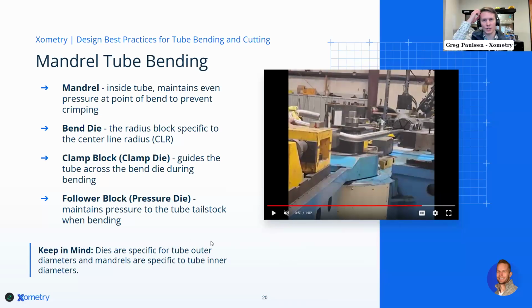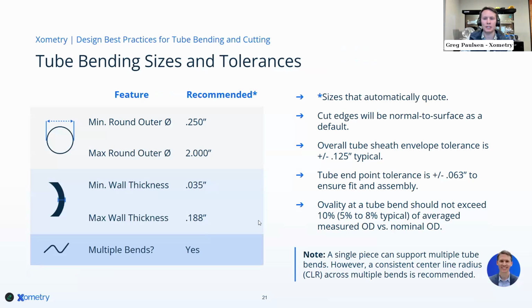And I think what's really important here is that this is very different from the hand bending tools you may buy at Home Depot. This is where you're looking at advanced manufacturing technology, because once you have these tools and setup, you can repeat and repeat and repeat with this. It is very powerful for multi-bend tubing at low volumes, but it really shines when you're outfitting part of your assembly line with these items, or you're making a stock item where you're repeatedly producing these.